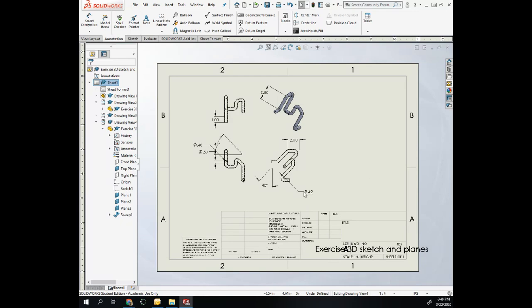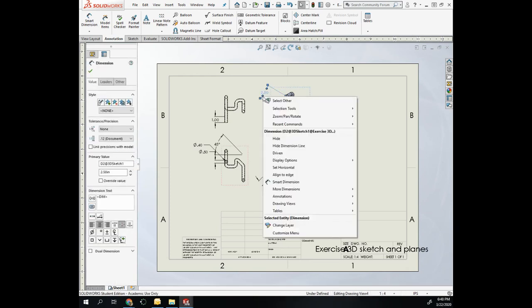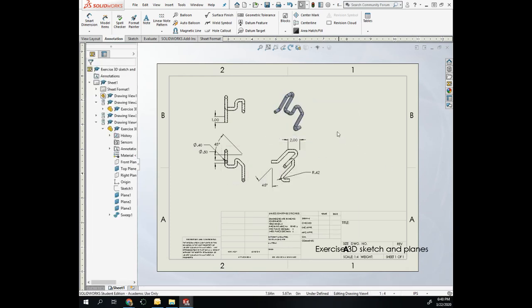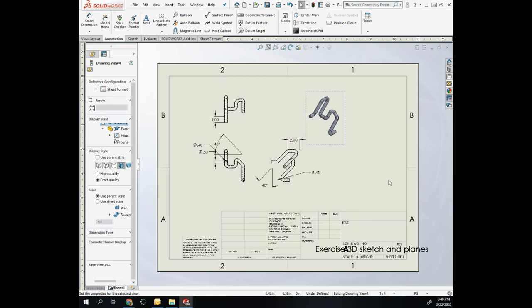I am expecting that you clean them up just to make it look a little bit neater. I don't know what it's going to take for that to happen with these drawings. Never have a dimension on your ISO. So I am going to right click and hide that and just find another way to dimension this. So that's laying out the drawing, model items, tangent edges, so on.